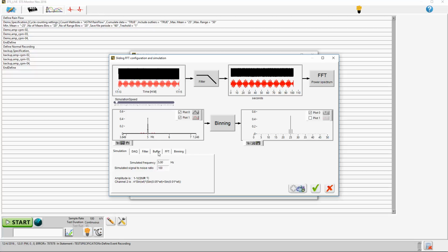The output of the FFT is sent to a binning routine. So here's the setting of the FFT. This is standard Windows. The window means that the incoming data record, let's say that our data record here is 0 to 100 seconds, is filtered by a window. And the window is needed to basically make ends meet for an FFT. An FFT is a circular integral over your data pattern. That means that the 0 point here has to match the 100-second point.